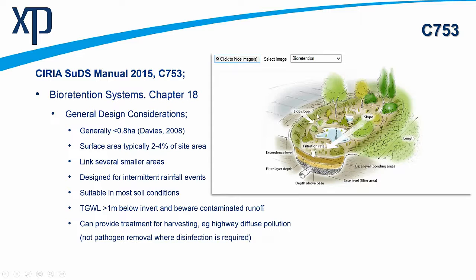That being said, if we put this right alongside a lorry park and you had a lot of highly polluted runoff coming down through into it, and we then infiltrated into an aquifer, you'd have to be careful, and we'd have to maybe have a forebay area and have the opportunity to be able to cut things off if there was a pollutant load that hit us through a lorry tank bursting, or high concentrations of pollutants coming off of such an area.